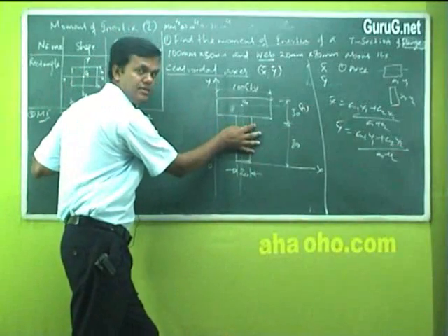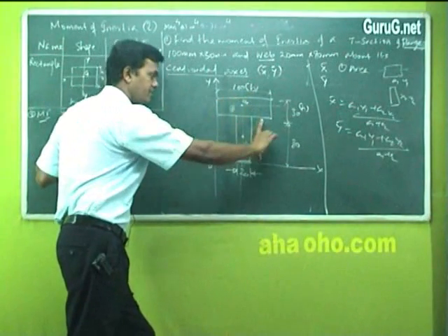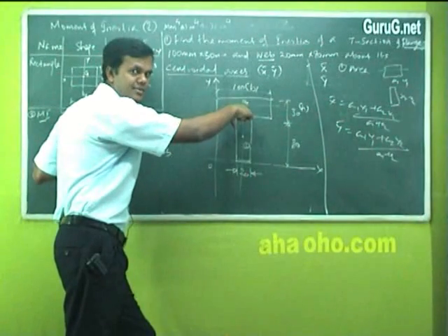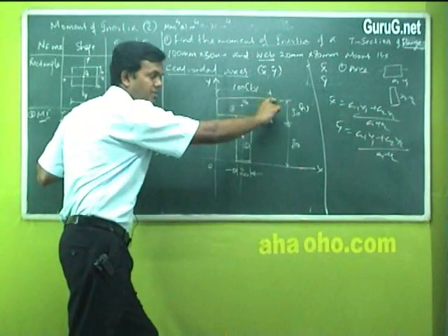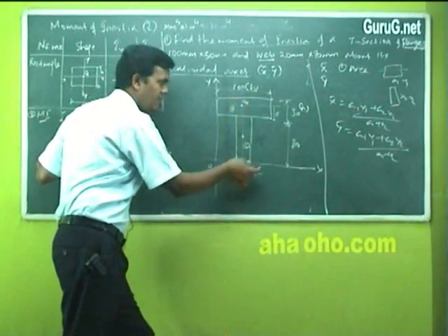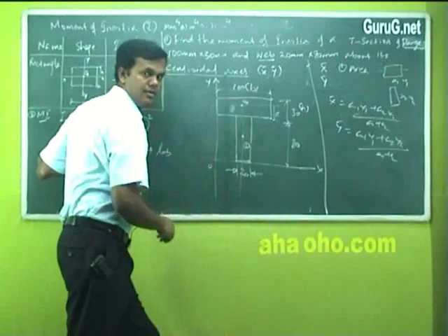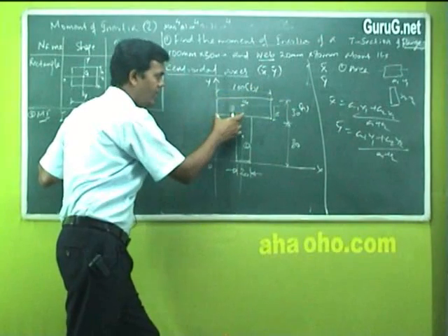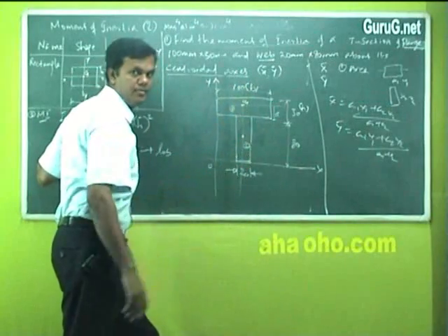For this particular body, I have to travel a distance. This is a separate sketch. From this 0x, I should travel some distance to touch the central axis. Is it not? This is 80 here. Somewhere the 15 out of 30, the center will be 15 millimeter. This is 15. 15 millimeter is the center point of this body from the bottom if I travel. Suppose if I travel from this side, from 0, to catch the center of this body, the center is here. Where am I touching? I am not adding anything because I am going directly to this value. 100 by 2 is 50.